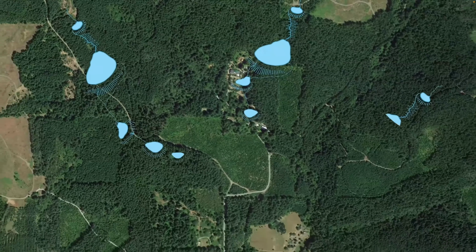Now, a key is really critical for assuring that the water doesn't move through the dam. As water moves through a dam, it sort of drops as it goes. It would slowly wick through a dam, and if it hits an interior clay core, a really well-built key core will prevent the water from moving all the way through the dam, which then would prevent channeling and piping through the dam that could lead to erosion and the blowout of the dam. It'll also just functionally keep water in the pond.